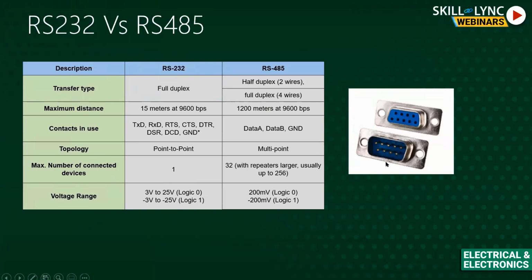The main purpose of using RS485 is whenever you want to connect more devices, and also when the distance limitation is greater. Both are the main advantages of RS485, because RS485 is differential based.